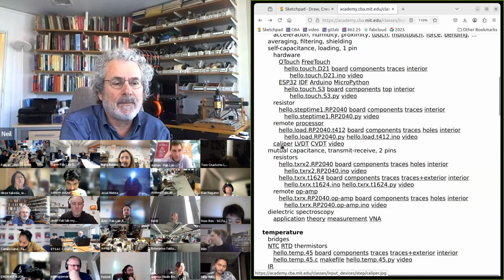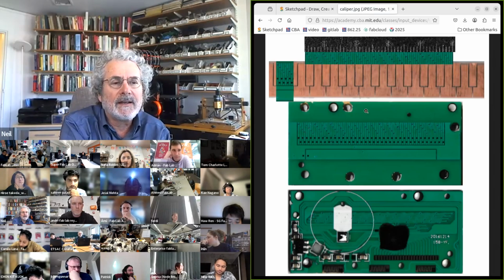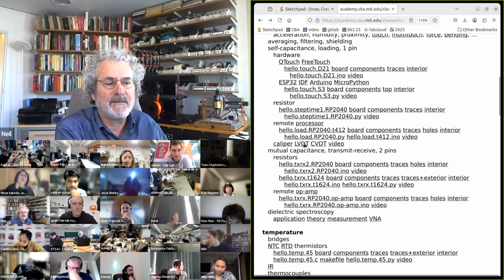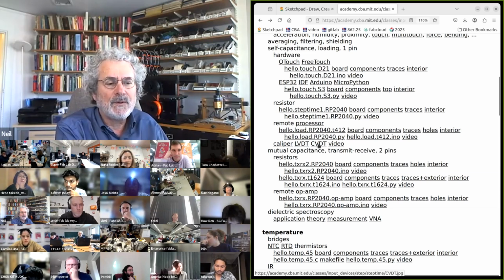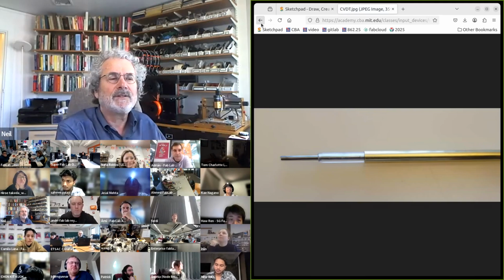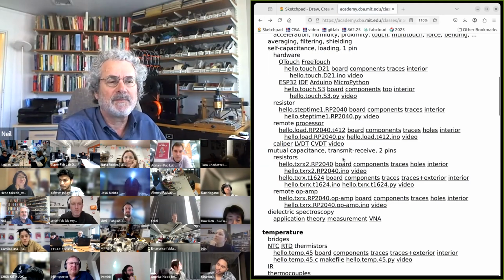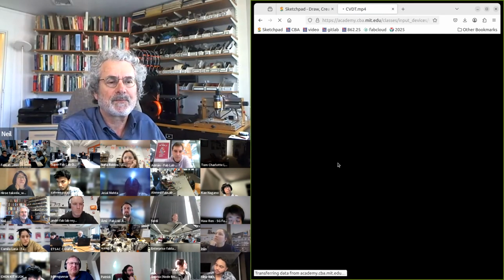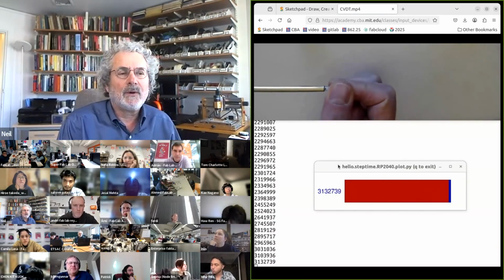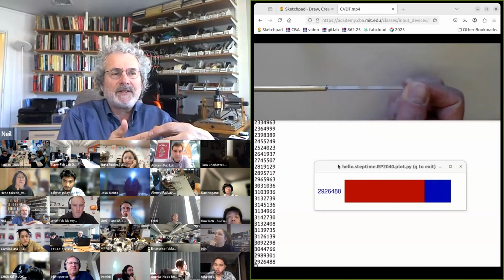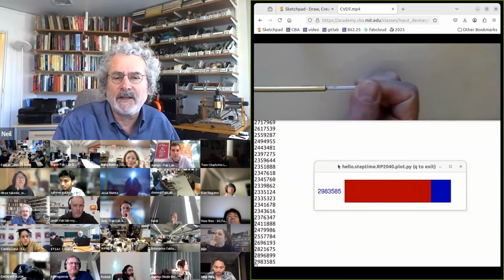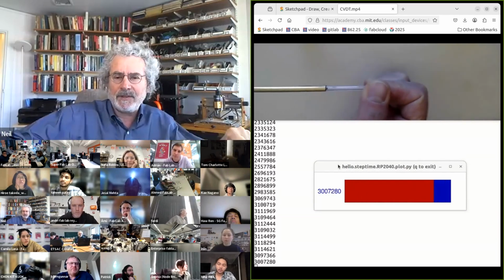And so this is how digital calipers work. These are the electrodes inside of them. Here I'm using this to make a linear sensor where I measure the capacitance between an input and an output. And so I'm just measuring capacitance between the inside and the outside. And when the dielectric comes in and out, I get a signal. So I'm using that to make a position sensor.